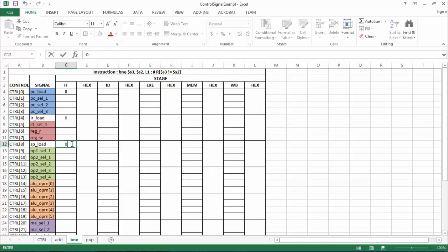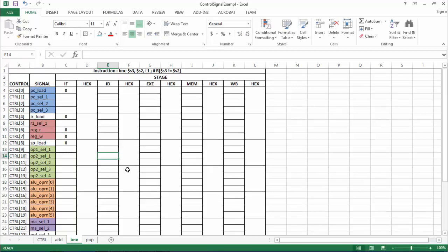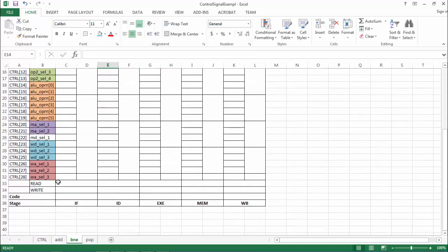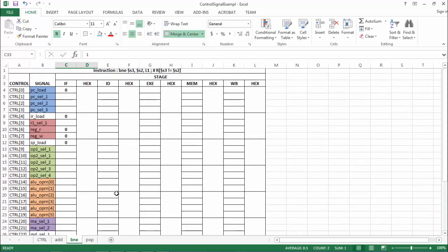We don't want to disturb the stack pointer. So those are all zeros. However, the register instruction fetch, we don't want to do anything, just hold there, right? And then we want to do the memory instruction read. So that has to definitely be a read signal for the memories. Okay.